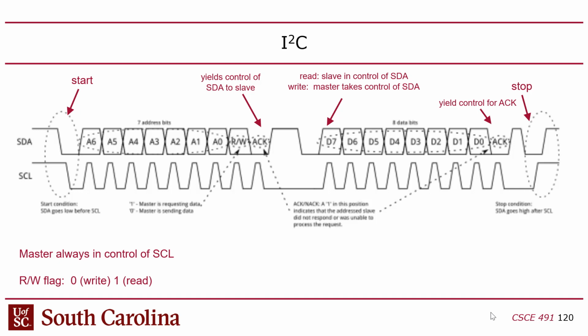These signals are both inputs and outputs on all the chips that are on the bus. So they're driving these wires with the pull-down transistors, but they're also sensing the voltage of those wires too. So they can sense a collision. So there's a mechanism that comes into play if two devices try to pull down and start a transaction at the same time, right? Just like there is on Ethernet, for instance, right?